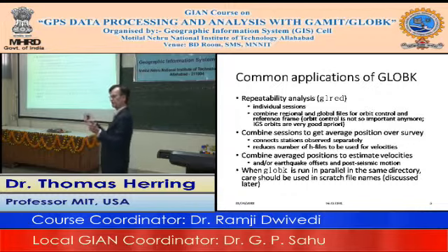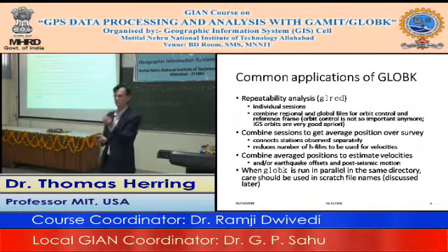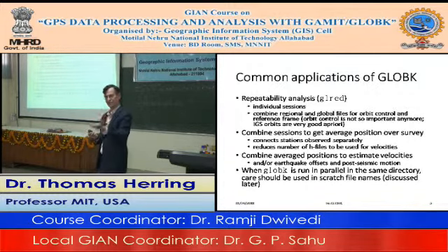One of the things when you get a lot of data, the thing you will find is a problem: every time an antenna is changed, typically the station position changes. Even if it's the same brand antenna that's put back in place, even though you know you've done force centering on it, which brings it back within sub-millimeter of where it was, you'll find the apparent position changes by a couple of millimeters. And that has to do with the phase center variations on the antennas and on the local multipath environment in some cases as well.